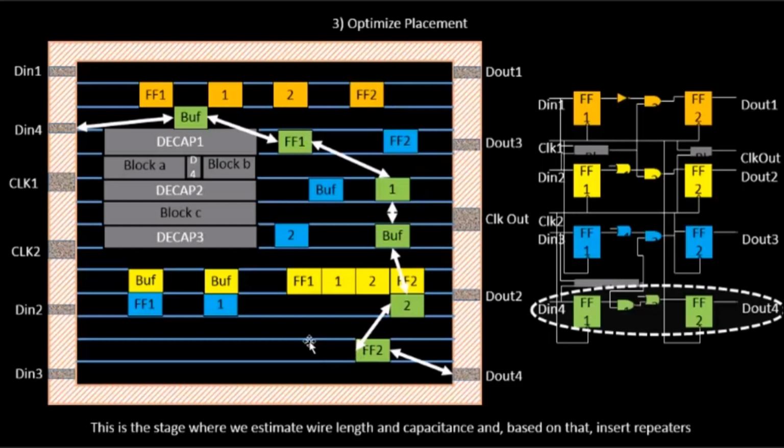So based on the ideal conditions of the clock, let's do a timing analysis: a setup timing analysis, and not hold, basically. Hold will not make any sense when we don't have the clock. So let's do a quick setup timing analysis with ideal clocks.